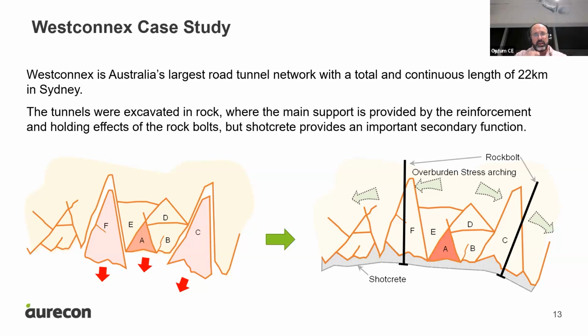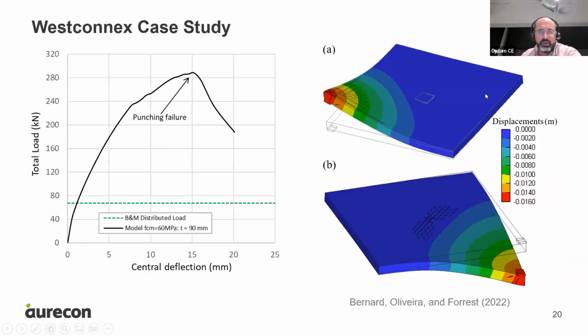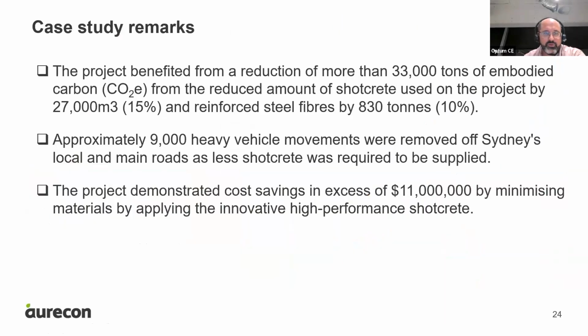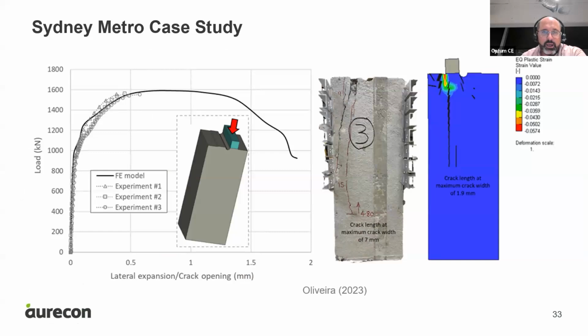When I said that I allowed the crack to develop longer, if you look at the test results, you can see that even in the testing, the crack opening at peak strength was in the order of 0.5 to 0.6 millimeters. Obviously this is ULS. That's why I said with bursting and splitting, the cracks you work with are smaller than in flexure. In ULS, 0.5 to 0.6 millimeters is a reasonable number to compare. A number of researchers have found that this number is indicative of a potential peak value.